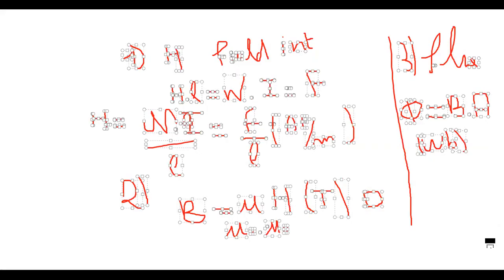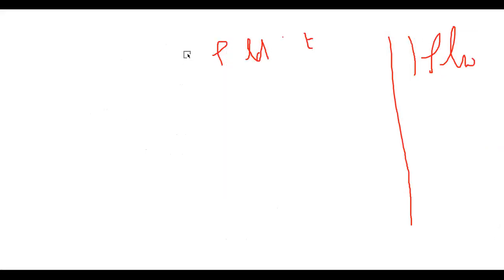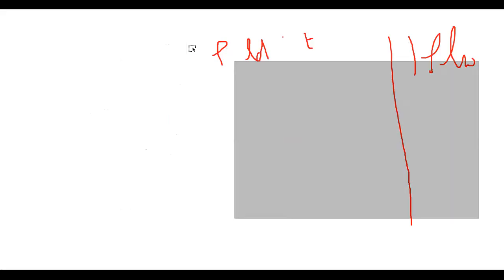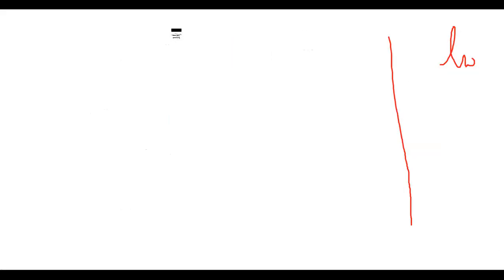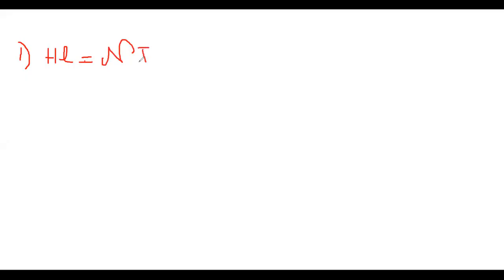Let's go over them quickly, in order to save those expressions in your mind and not forget them. I know we did them a bit yesterday, but today we have more attendees, which is good of course. Firstly we start with the magnetic field H. We said HL equals NI, which implies that H equals NI over L. This is the magnetic field intensity.